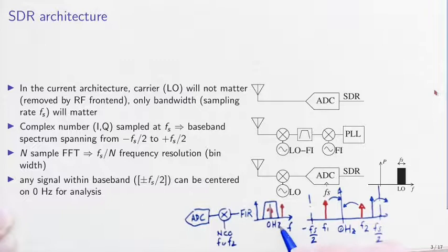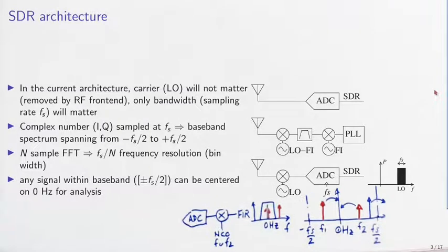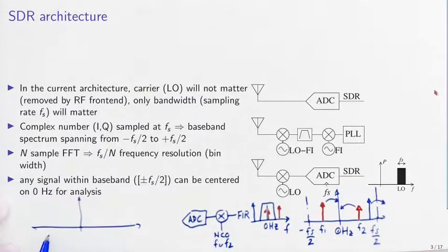One last item is that when sampling n samples of data in the time domain, because of a one-to-one relationship between frequency and time domains, when we sample over this sampling band of fs, the sampling frequency, in the frequency domain, the n samples that were collected will lead to n samples in the frequency domain.